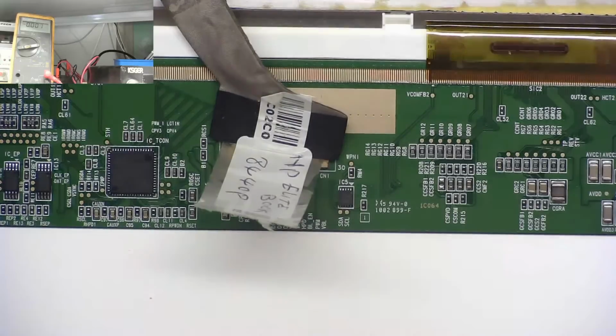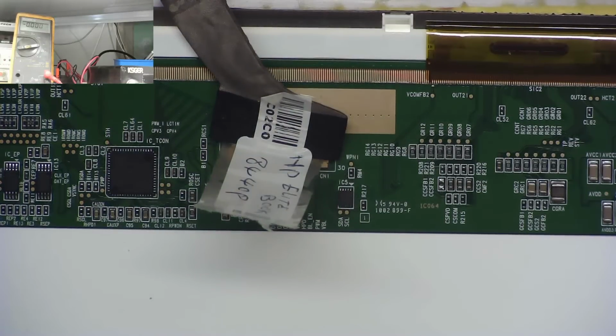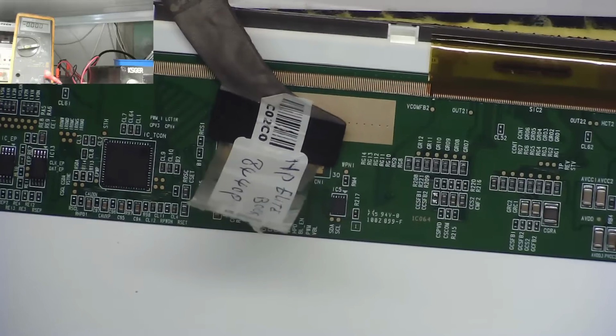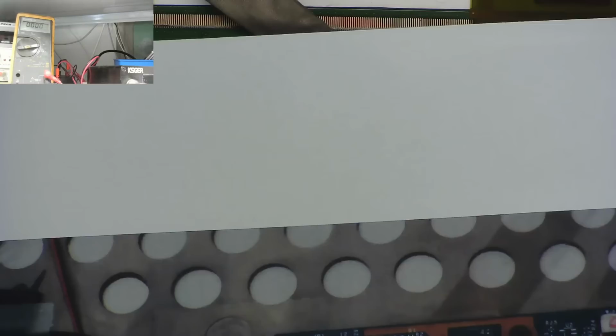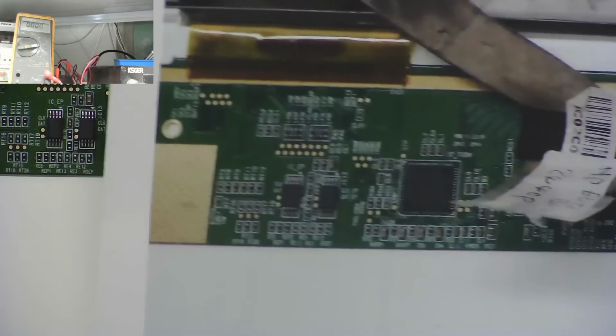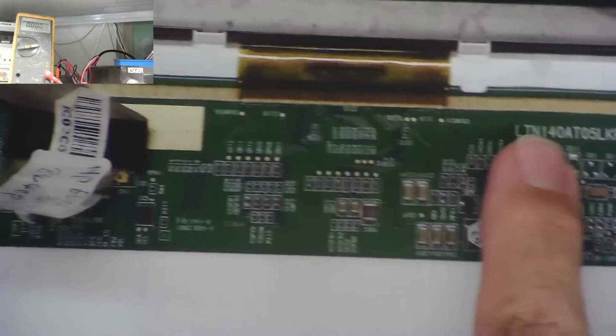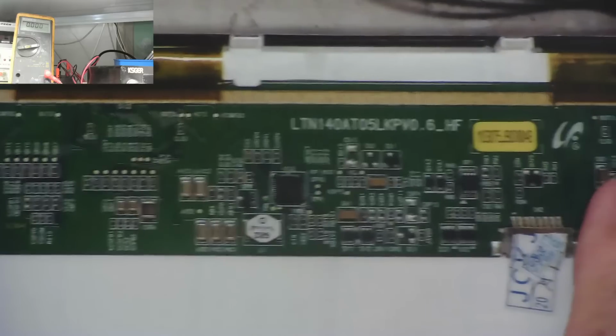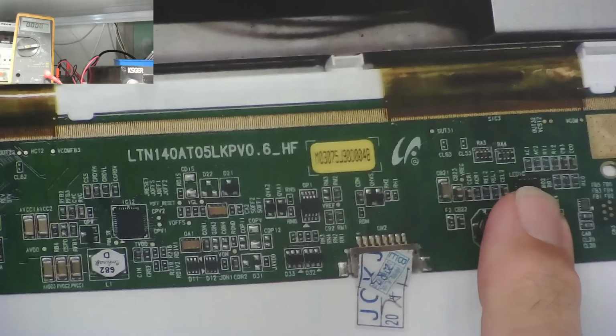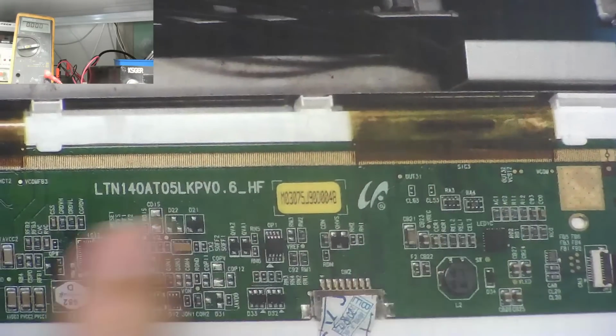I think I might just take a photograph of this, and then I can just draw on the photograph. So give me a few moments, I'll take a photo and print it out. Okay guys, what I've done is I've basically printed a picture of the board, and I can see that there's a lot of test points on this. So now I'll pause the video and go through all these test points, and I'll make a note on here of all the voltages.